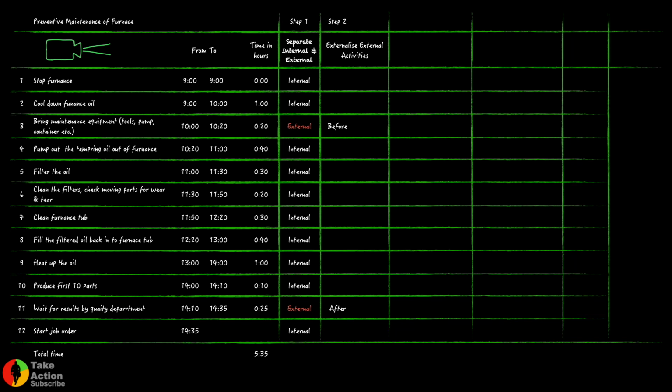The cost of 50 parts we should compare with the cost of not running the machine for 25 minutes every single week in the whole year. So with this argument, in my experience, all the time I have done this analysis, the cost of stopping the machine was always much higher than in case we have a quality issue and we have to scrap these parts a few times per year. So with that, we can keep the machine running and do the inspection when the machine is running.